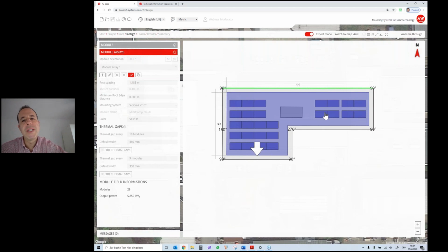And the idea should be that I have a bigger block of PV modules, because they resist the wind as a block as a whole. When you design, you should optimize. My recommendation is that you form as big blocks of PV modules as possible. So this block will now be separate from these two, and I will get much lower quantities of ballast than over here when I have 2 times 2 PV modules.